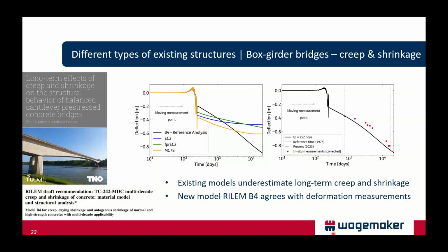Research was done by the Technical University of Delft and TNO, a Dutch company that does a lot of research on, among others, concrete structures. It was found that the existing models from Eurocode and Model Code underestimate long-term creep and shrinkage, especially if you go to several decades.